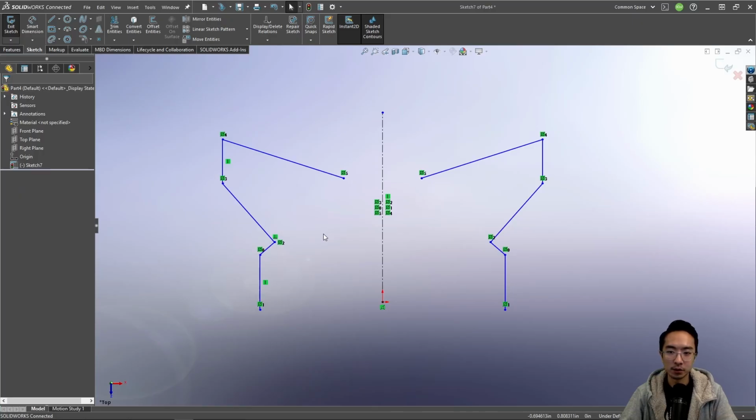And all the dimensioning rules that we talked about will apply. So right here, we're mirroring it about the center line. You could mirror it about any other direction. So you could go ahead and play with that. But that's pretty much it for mirror entities. It's great when you have symmetry, and that way you don't have to duplicate both the right and left two times.